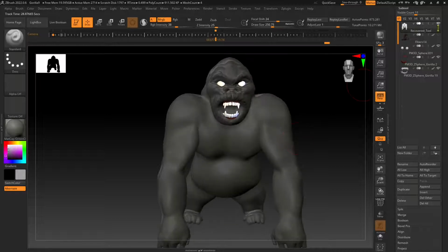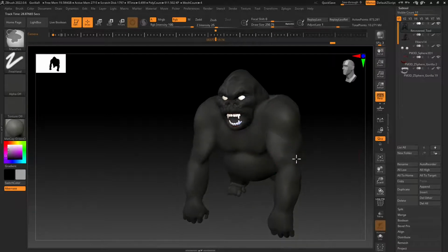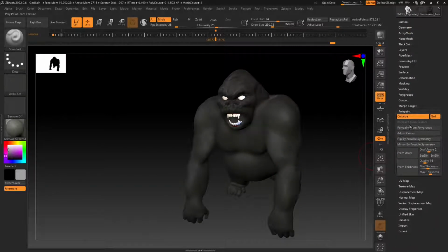Now, another thing you want to check is the little brush button there, because that's actually the visualization. And you can also go to the polypaint panel in the tool shelf. You can see there you can activate and deactivate colorize, which is essentially the possibility to put paint and visualize the paint on top of that.